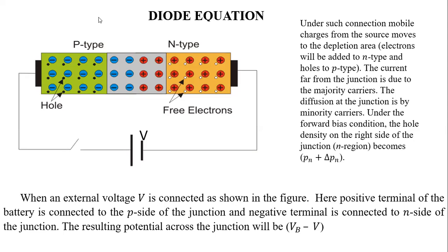Okay, so this is our p-n junction. We know that inside there are free electrons associated with pentavalent atoms, and this is a junction like we discussed. The electrons from those pentavalent atoms near the junction diffuse towards the p side, and they transform into positive ions and negative ions, thereby forming a space charge region. We also know it as a depletion region.